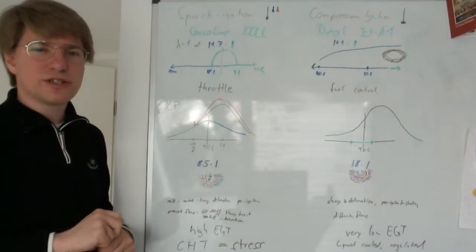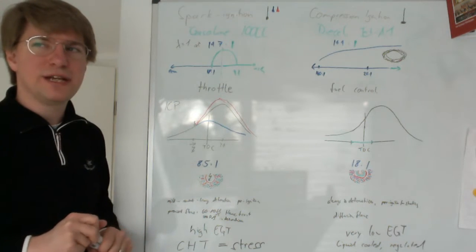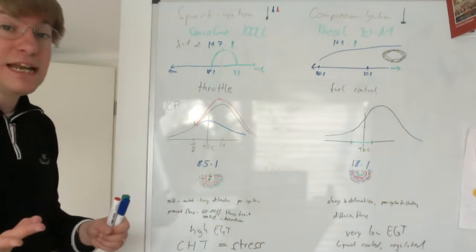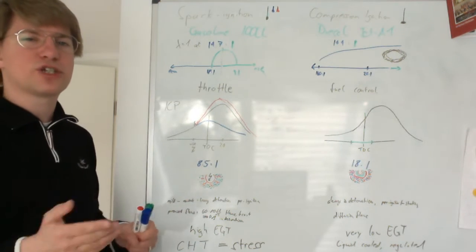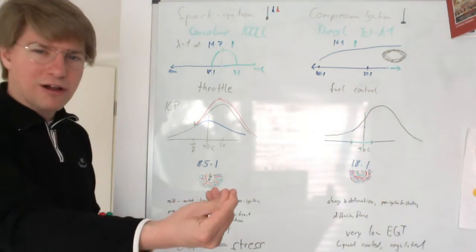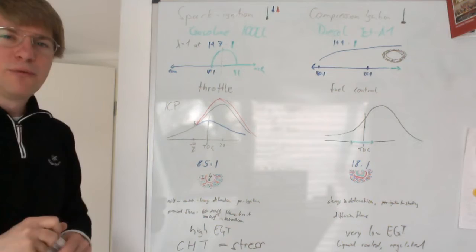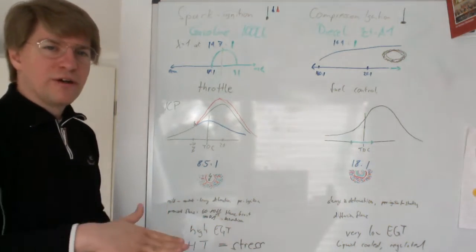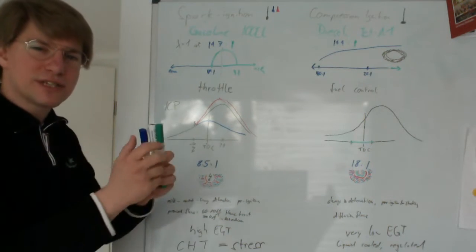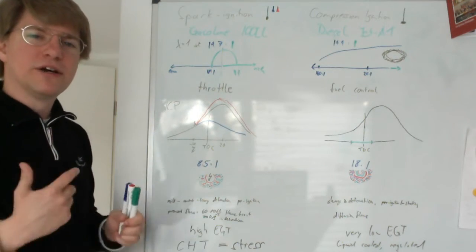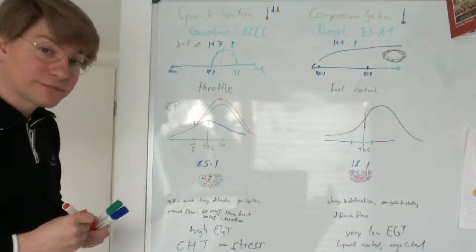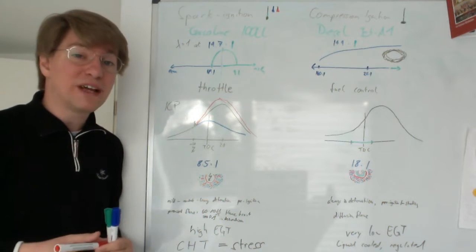At a slightly richer setting, like 100-150 degrees rich of the peak side, which is where we want to be for sea level takeoff, and this is how the full rich setting of our engine is usually set. So when the mixture knob is all the way in, the red knob all the way forward, we are at this mixture for a sea level takeoff that yields this 60 to 80 feet per second flame front movement through the combustion chamber.